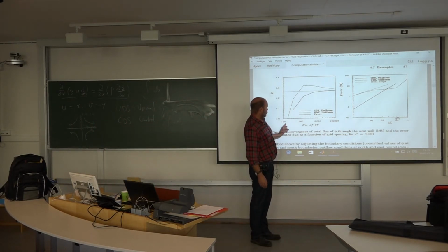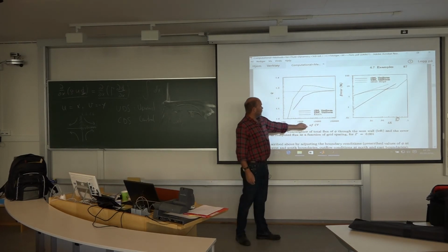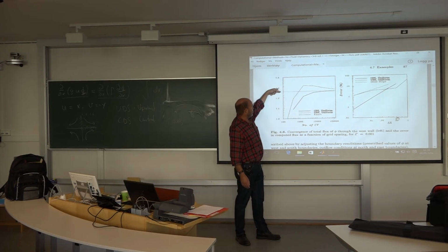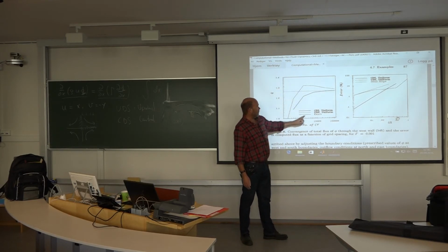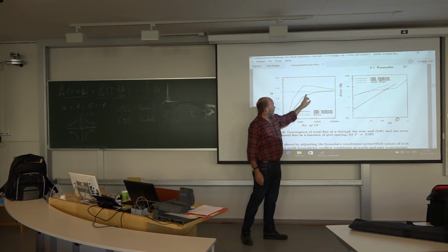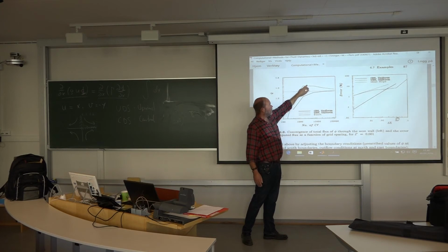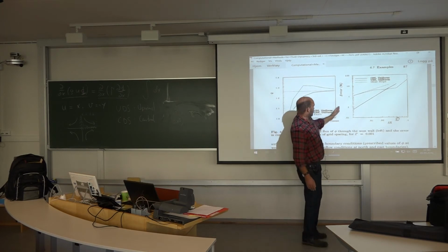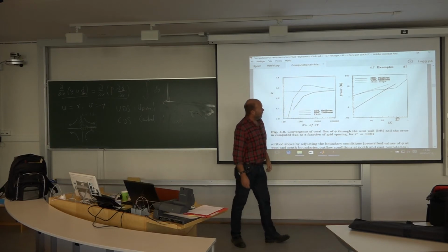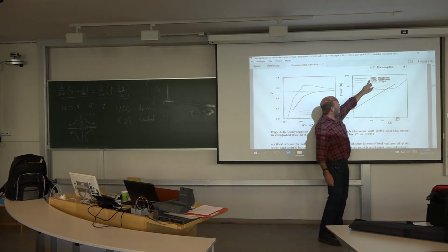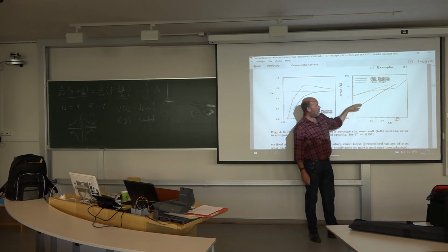And here it's just the number of cells you have versus the correct solution, what it should be. And you see clearly the central scheme has a much smaller error than the upwind scheme. Here is plotted also with a log-log plot, and you see the central scheme goes as a straight line with a slope of 2.